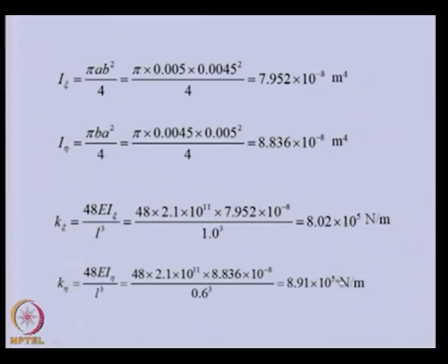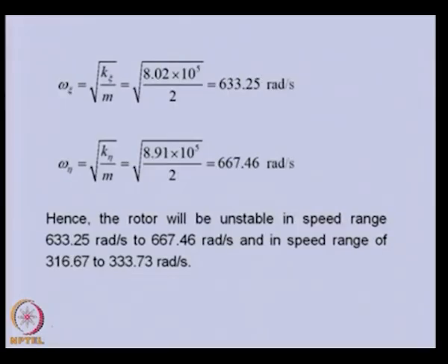So there is slight deviation because of the elliptical cross section in these two. Now these two parameters, omega xi and omega eta, can be obtained as it has been defined. So the range is this one, the omega xi is this and omega eta is this much. So now, as we analyzed already, if the rotor is operating below this two-speed range, we will be having unstable operation.